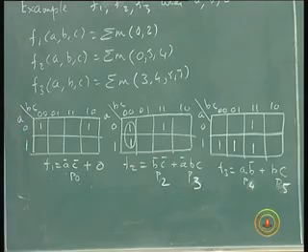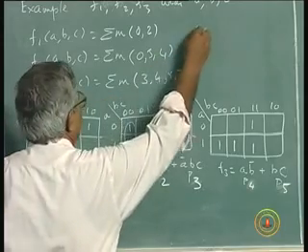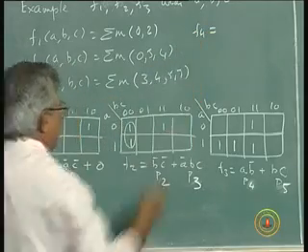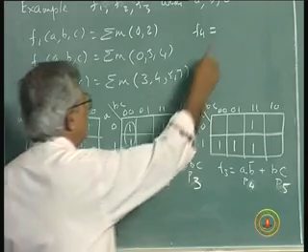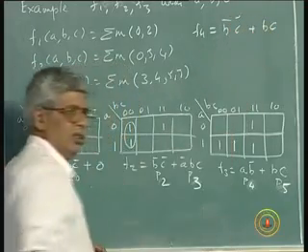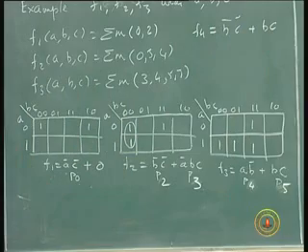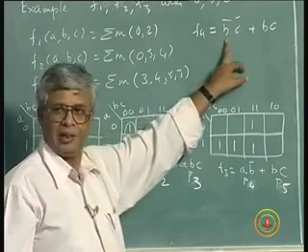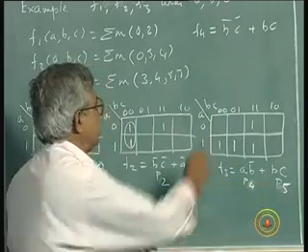Now if I want F4, which was originally thought as what? What is F4 again? B bar C bar or BC, is that right? Is that right what we wrote a little earlier? In which case, B bar C bar is P2. I cannot use P2 here. I have to redesignate this as P6 and P7